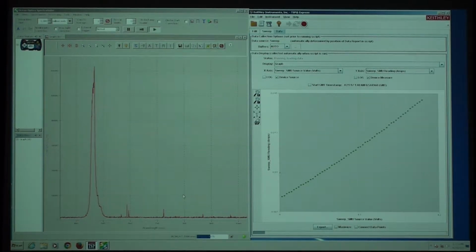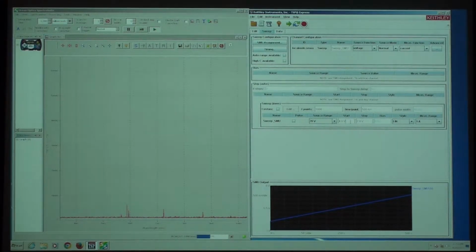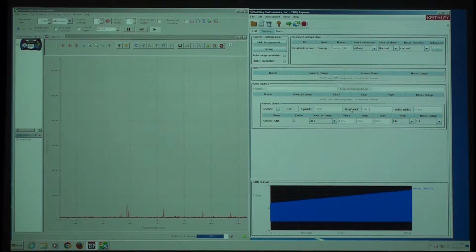So now we're going to do the laser? Yeah, let's try. So to get that, not to burn the laser and to make it lase, we actually need a pulse mode for that. So we're going to use 100 milliseconds here. I'll change the settings. That's just to avoid too much heating. You just have pulsed injection rather than direct, continuous wave.